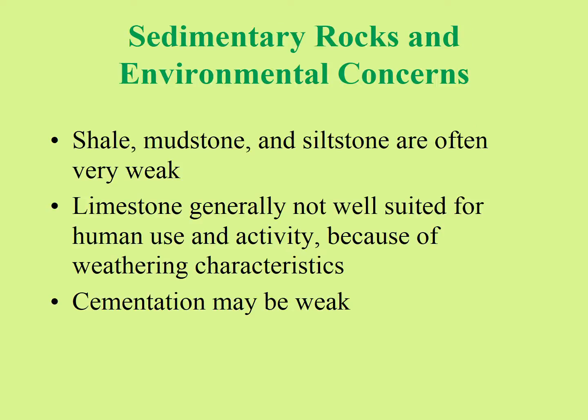Regarding environmental concerns associated with sedimentary rocks, we have to recognize that shales, mudstones, and siltstones are often extremely weak and prone to weathering quickly. In a matter of a year or two, you might be able to see weathering occur to some of the most weakly cemented of these rock types.